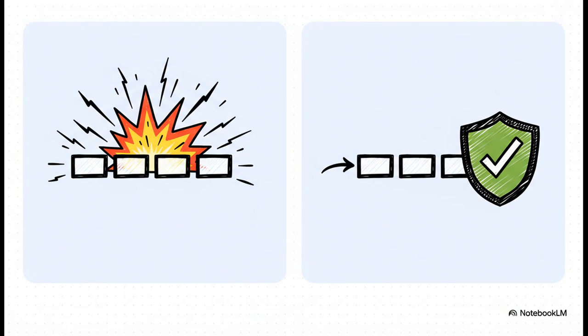And here it is, the big aha moment. Let's look at our risky 7 to 8 transition again. In standard binary, it's that messy 4-bit flip. But in gray code, the value for 7 is 0100, and for 8, it's 1100. See it? Only 1 bit changes. It's just so clean, so simple, and basically error-proof.